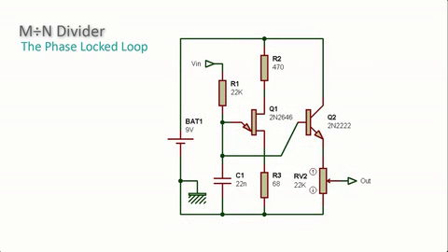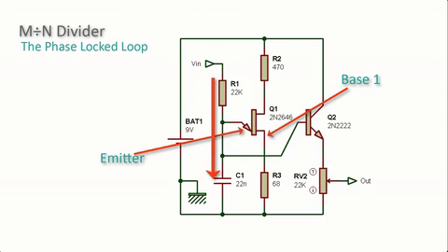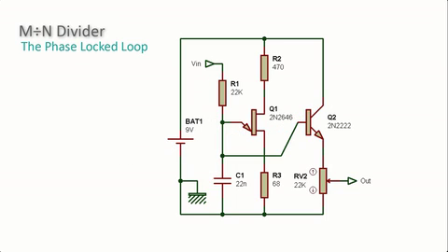There are lots of ways to build a voltage-controlled oscillator, but this one is tried and true. Now, Q1 is a unijunction transistor. A UJT has a single p-n junction at the emitter. Because of the way the UJT is constructed, the emitter base 1 circuit exhibits negative resistance, so as C1 charges through R1, the emitter pin does not conduct until, at a certain threshold, it suddenly does, dumping all the charge on C1 through R3. Then the UJT turns off and goes back to blocking until C1 charges sufficiently again.